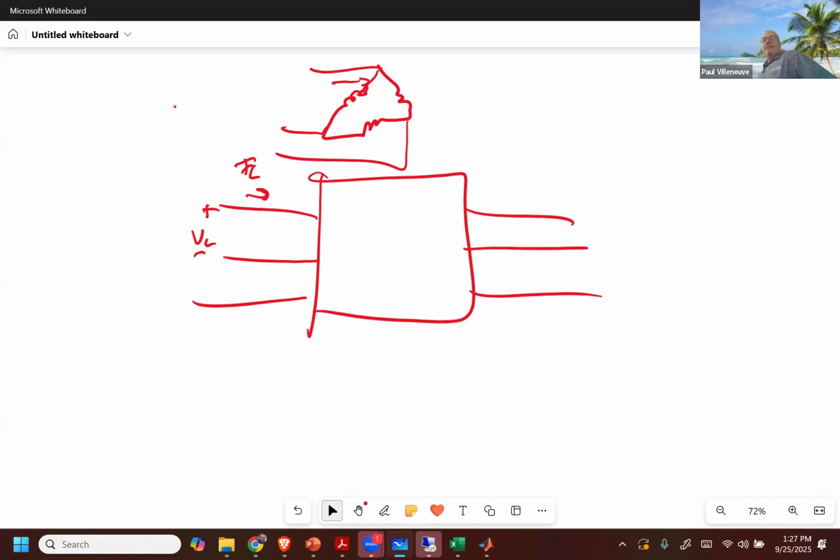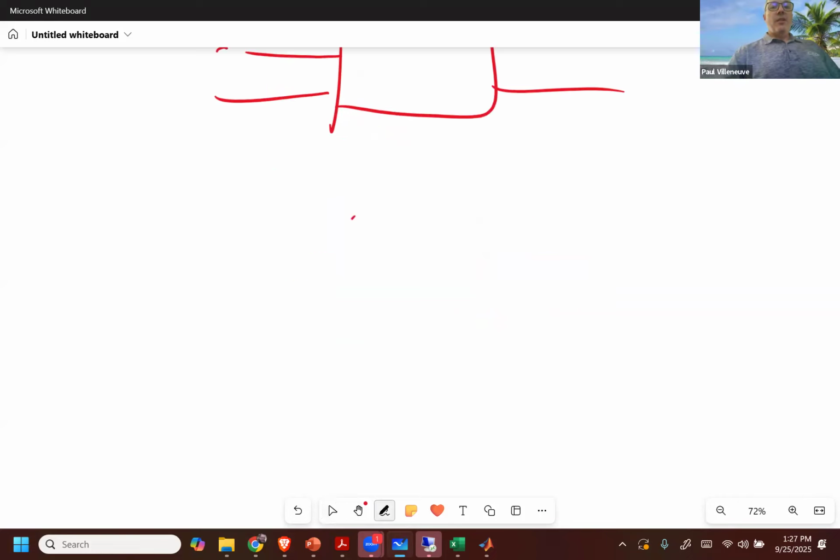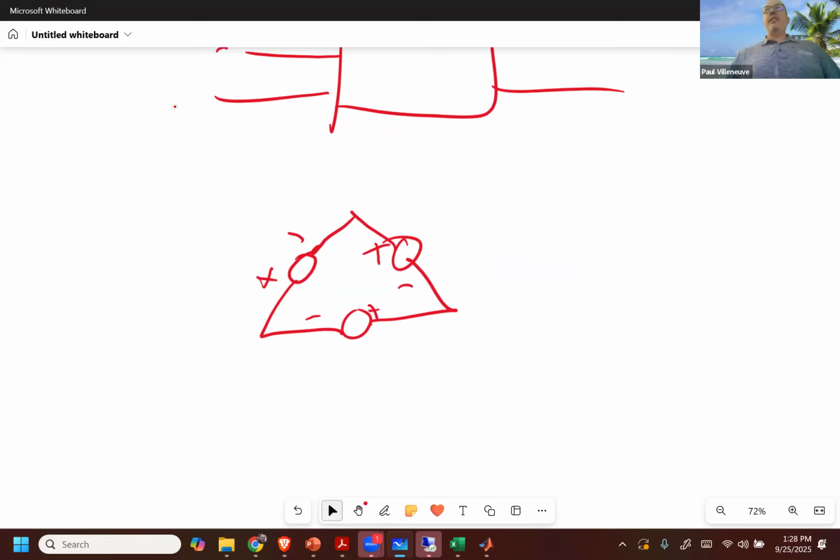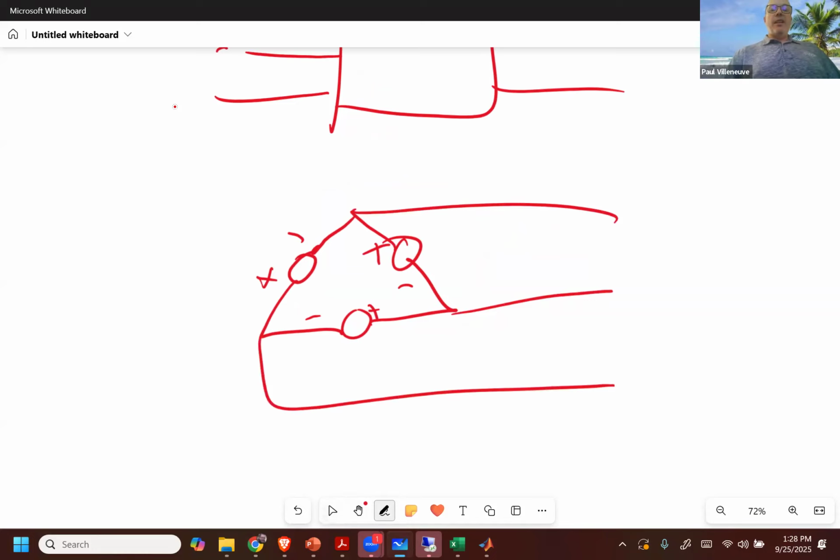I feel that in the 3-phase, they calculate line and phase quantities. Could you give an example? Yeah, so if I have a delta here, the way the delta is connected is in a tip to tail fashion. So remember, the phase quantity is always looking across a single phase. So this is a single phase power supply. I've got 3 of them in here.